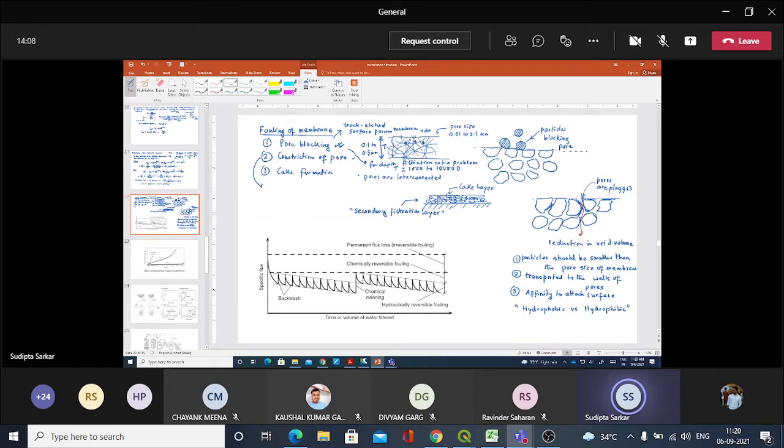These materials on the surface are greater in size than the pore size of the material. And when they are deposited here, they will offer more resistance, or less path for other smaller particles to pass through, and basically you end up removing particles much smaller than the pore size of the membrane.